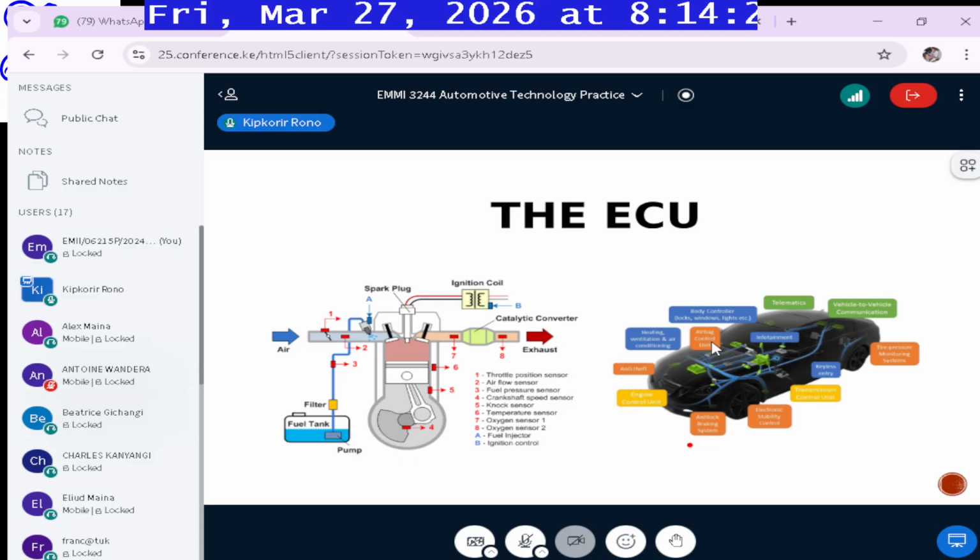If you do that, it means you are also limiting the amount of power that will be produced by the engine. That's why when you are in eco mode, it's usually a fuel saving tactic. It's meant for the engine to take in the least amount of fuel while producing just the right amount of power required for that operation. If you go to sport mode, usually it's wide open throttle, WOT. So you are letting in a maximum amount of oxygen through the air, which will mix with fuel, and you get the most power.